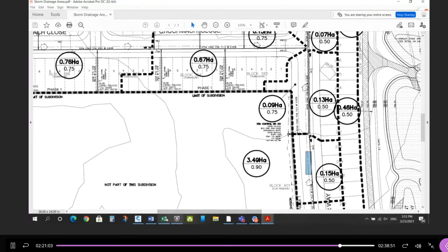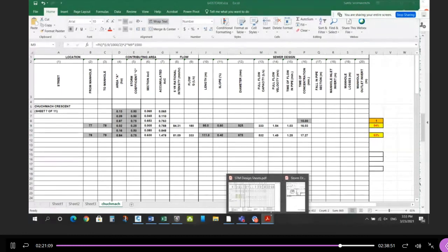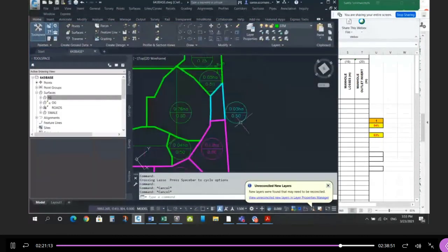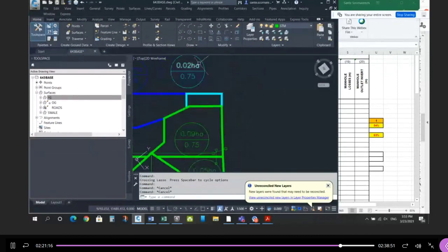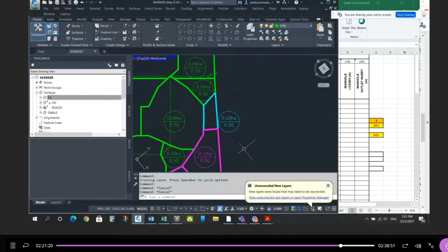Okay, and you can look at the areas. You can look at the areas to a certain extent. They're very, very small. They're not insignificant, not like sanitary sewer, right? But 0.02 and 0.03 are very, very small increases. Will the expected flow change? Of course, but they probably won't exceed the capacity of that pipe that's already in the ground.